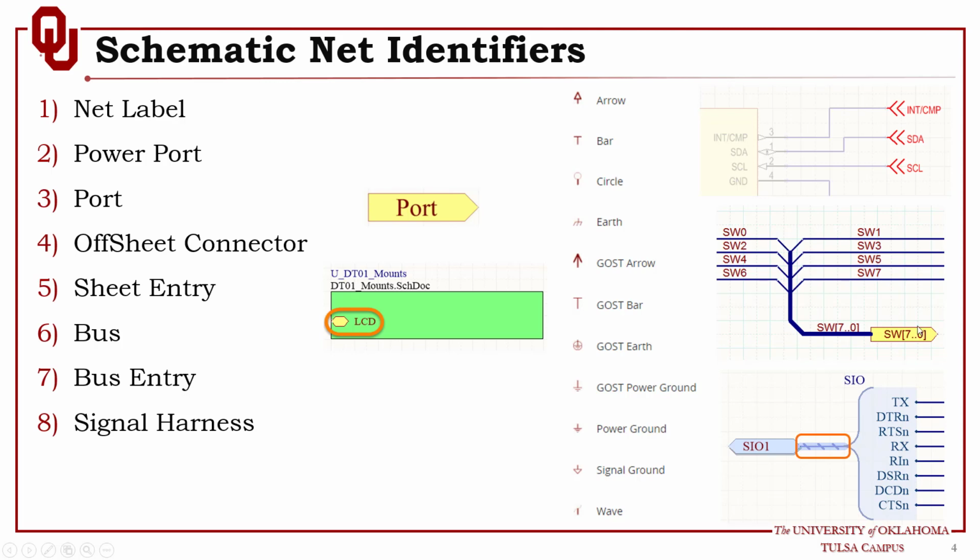The bus entry is basically similar to the board, as you can see in here. This is a bus entry. It's similar to the board, but you can call it bus board or port or bus entry. And basically, it's a graphical representation, nothing more. You don't have to put it because we count on the label on the bus rather than counting on the bus entry, but it's just an extra graphical representation.